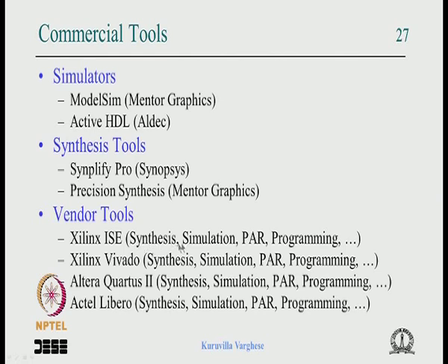You have synthesis, simulation, power, programming, static timing analysis, constraint editor, power analysis, floor planning, name it, everything is there. And this ISE tool works up to the chips of the family Spartan-6 and Virtex-6, but for Virtex-7 they have a different tool, a much better tool called Xilinx Vivado, a very good tool, a quantum leap in the whole tool technology.